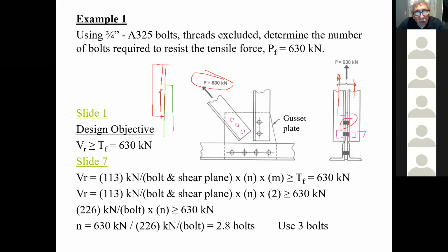Fair enough. And here, I'm going to change color again so that we can all see it properly. And here is my bolt. Just worry about one bolt for now, okay, Andrew? So can you appreciate that? Change color again, make it blue. Can you appreciate that this is what's pulling here, my TF, right? And this is my gusset plate here. Therefore, the shear plane between the bolt and the gusset plate is right here. Do you see that? So that's one here, right?